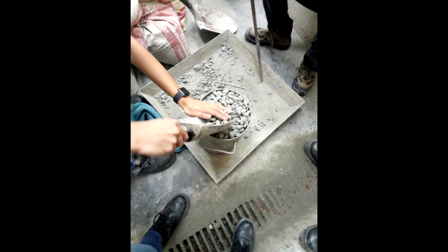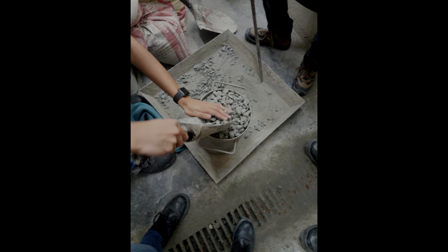For coarse aggregates, all three methods were used. For fine aggregates, only the rodding method was available. These are based on standard testing methods. For the procedure of the experiment, the rodding method was done by filling the container with 1/3 sand and rodding it 25 times. This was repeated 2 more times until it was full. 3 trials were done for the fine aggregates, while only 1 trial was done for the coarse aggregates.